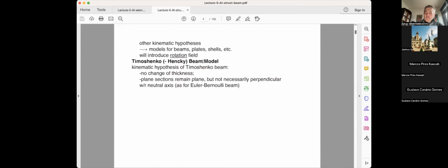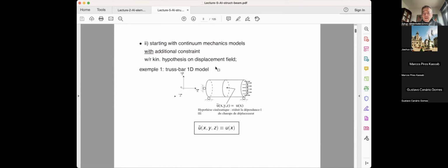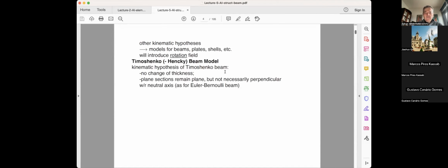But you can also go for the beam model. If I take the same type of structure and I now apply transverse loading, then the structure will typically bend, changing shape from rectilinear to some kind of curvilinear because of the bending. And it so happens that I can make a hypothesis on how the displacement would behave in such a case, given that the cross-section is very small.